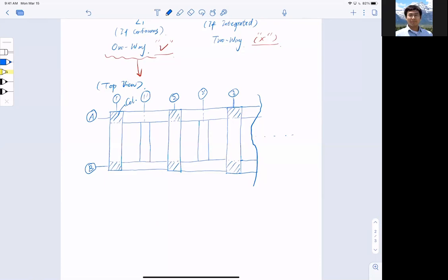Now, I need to show you the directions. What are the one-way slab directions? Using red color here, if I take the center of this beam and the center of this beam, you see I'm not going just from the main beam. This 1 prime is still considered a beam, and this is L1, the bending direction.